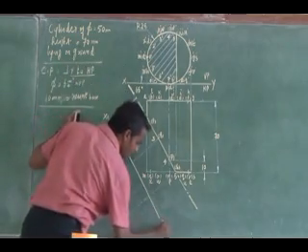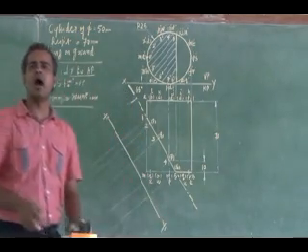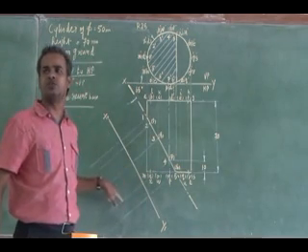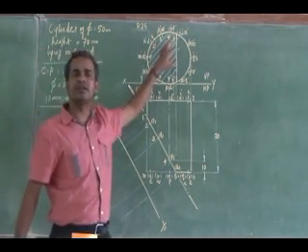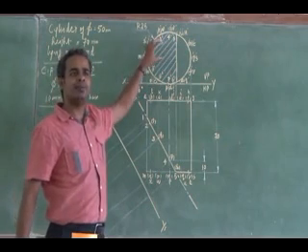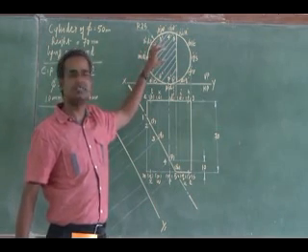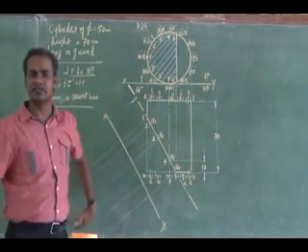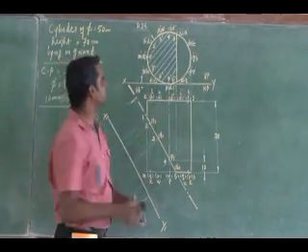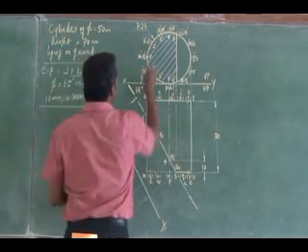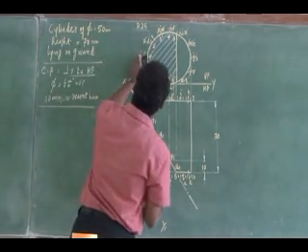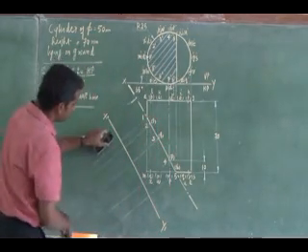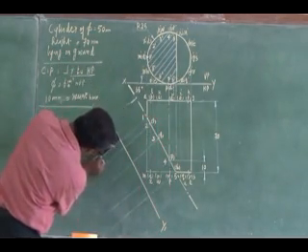Y1. Listen, how can I mark the cutting points and obtain the true shape? You transfer the apparent cutting point distance from the old reference line to the new reference line. From the old reference line XY, measure the cutting point distance for 1, transfer it from the projector 1 and mark that cutting point 1.